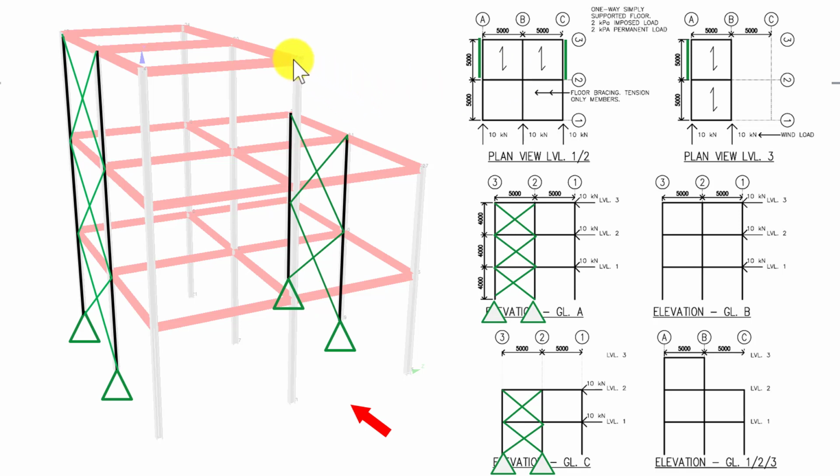Especially, let's say if I started up here, if there was a load applied right up at the top of the structure, I would somehow need to get that load to those foundations. So let's say, for instance, I put a braced bay down 1 story. That will now carry my loads down, but I'll have to spread it across to those braced bays. If I wanted to, I could actually take this brace all the way to the foundation, and then that would sort the problem out. I'd have 3 separate braced bays, and the entire structure would be stable in this direction.